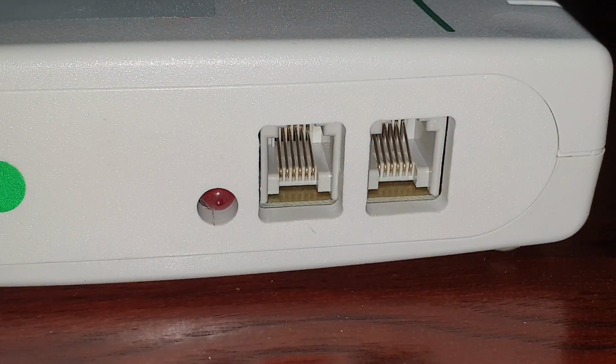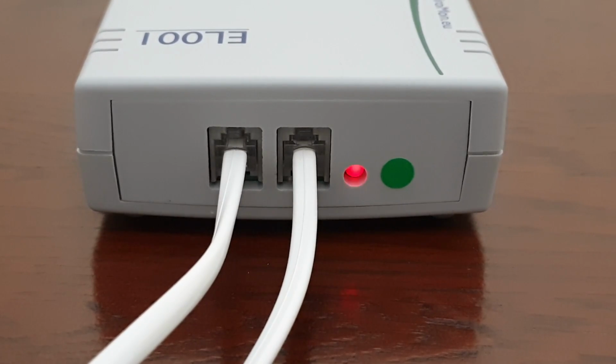A quick way to check if the logger or the converter is running okay is by looking at the LED. It should be flashing, as you can see here. This usually indicates that the logger or the converter is running okay. However, this isn't always the case. It could be that one of the actual network ports is running fine and the other network port is damaged, or there could be other issues.